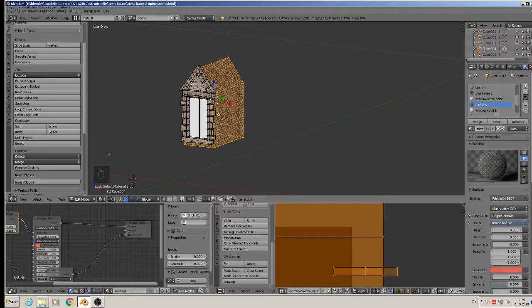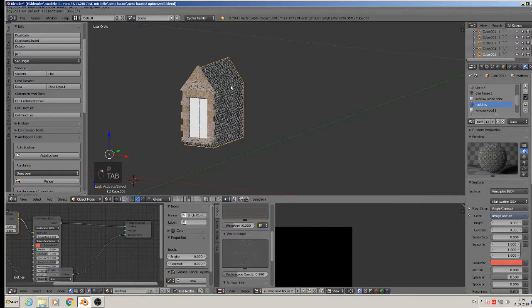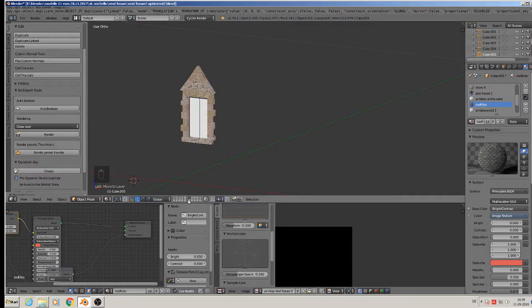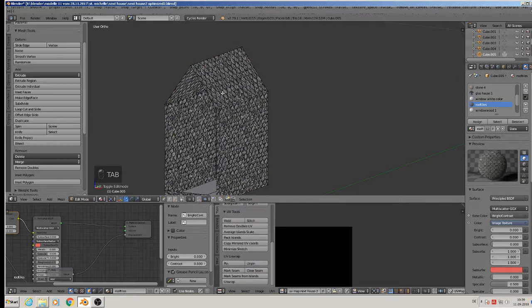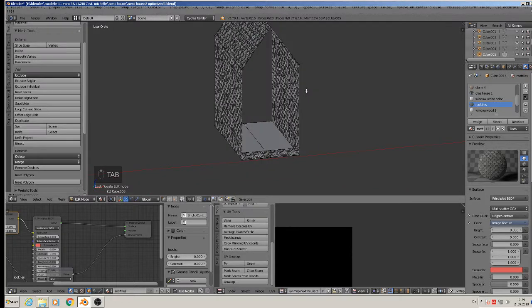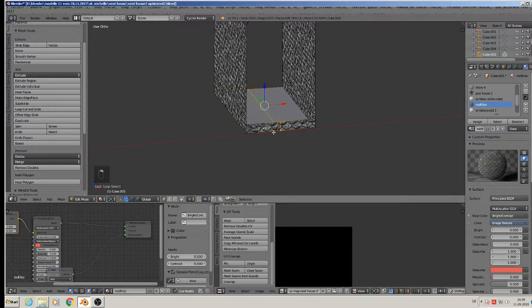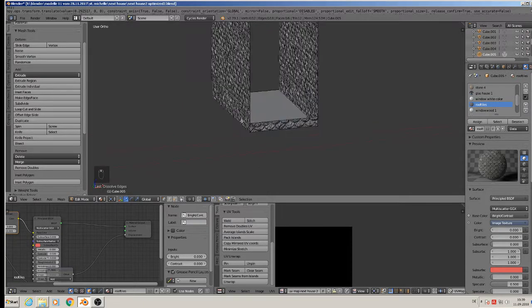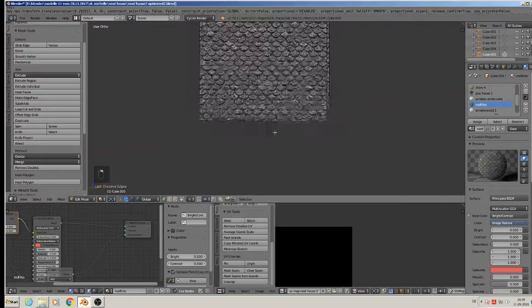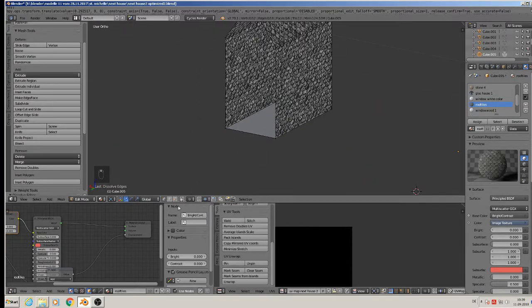So we move that to the 7th layer, but before we must separate the selection. Then get them, move to the 7th layer. So we add the 7th layer now here. Go in edit mode and we see that here isn't needed. So X, dissolve this edge. We will never see the end here. So you can delete that edge.